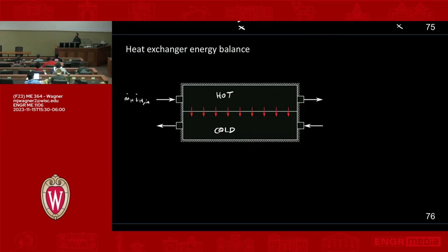Let's assume there's no loss of mass in the system, that what goes in goes out. So then on the right side we have m dot h, and we have ih out. This is not yet a differential analysis. We're just trying to do energy balances on the entire fluid all at once. So we're not doing the x plus dx thing.